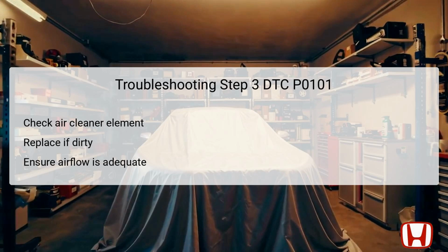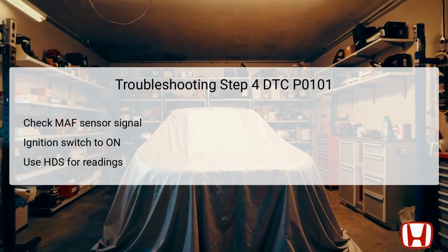If the air cleaner is clean, you can then move on to the next step in the diagnostic process. Failure to check and replace a dirty air cleaner can result in persistent issues and diminished engine performance. The fourth step of troubleshooting involves checking the MAF sensor signal without running the engine.